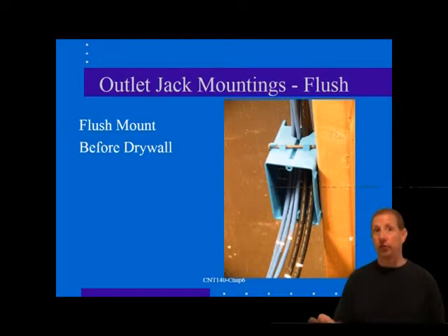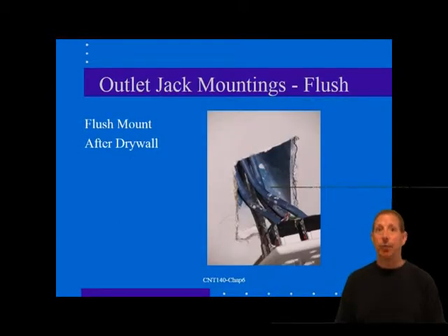The box should be positioned at the same height as required for the electrical outlets. This might not necessarily be a construction code requirement, but it does enhance the appearance of the final installation. The cable may be run through a bare knockout hole in the box or through a conduit or a flexible cable connector. Plastic sleeves are also available to minimize any chance that the cable might be damaged by the hole's sharp edges. Outlet boxes for post-wiring use are also available.